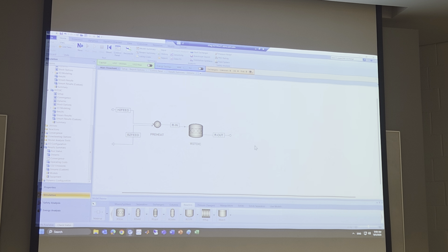But if you look at the temperature profile and pressure profile, maybe we can look at the pressure profile. If you see, the input stream to the reactor pressure was 330. We used that pressure drop information. As you can see, the output stream from the reactor is 315 psi. Okay? Good. So far so good, then we can continue to add more unit blocks.